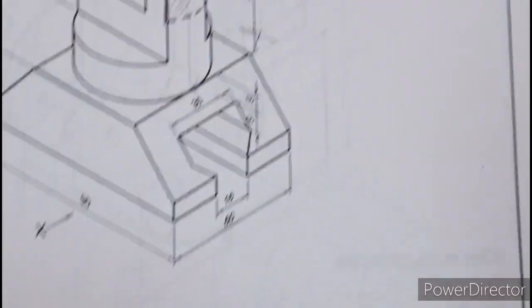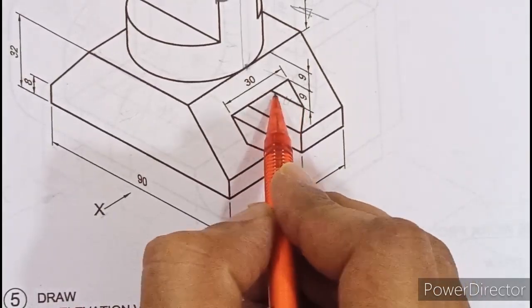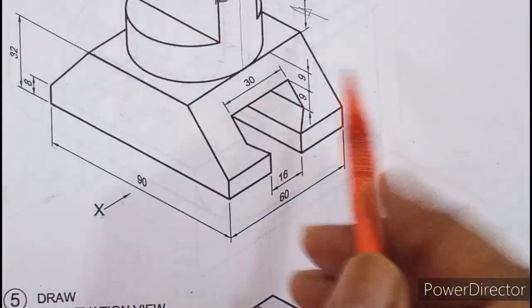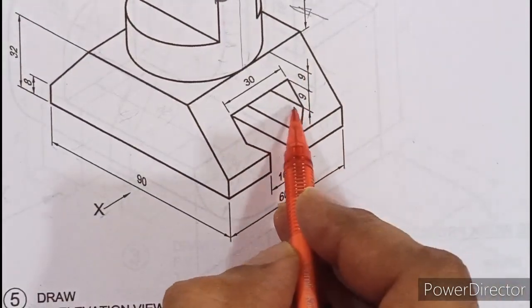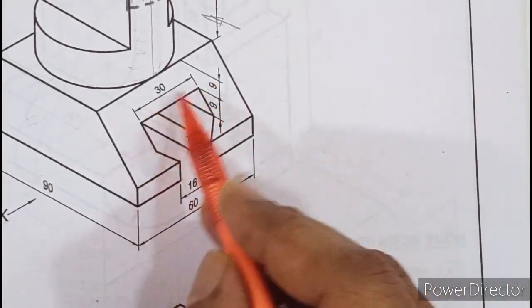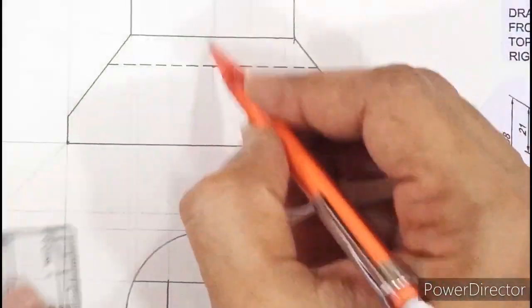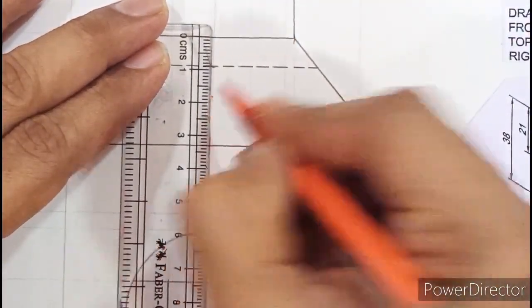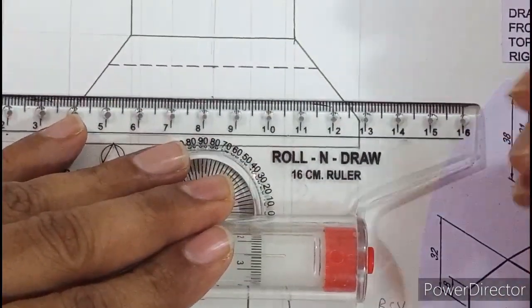Similarly, if you look at this diagram, you cannot see this edge going inside, the second edge. And if you look at the dimensions, from the top of the platform, it is 9 plus 9, 18. So if you come down by 18 from the top of the platform, you're going to get the second hidden edge of the slot. So there is a trapezoidal kind of slot. For that, 1, 2 and 3 hidden edges are there. So the second edge is 18 from above or 9 from the first one. So let me mark 18. Okay, I'll align the roller scale with the previous hidden line. Roll and draw down.